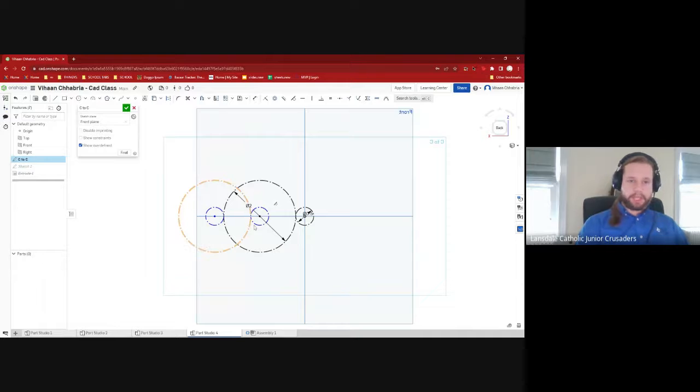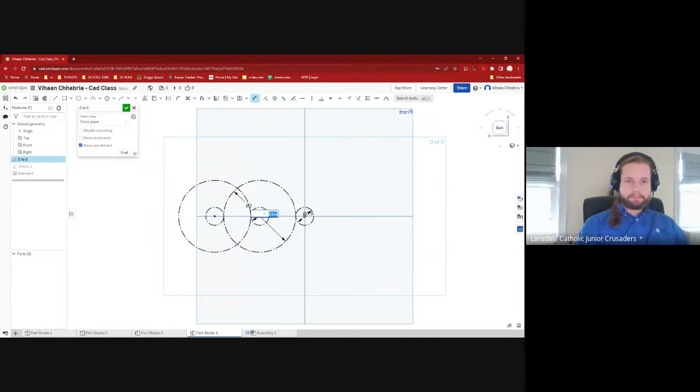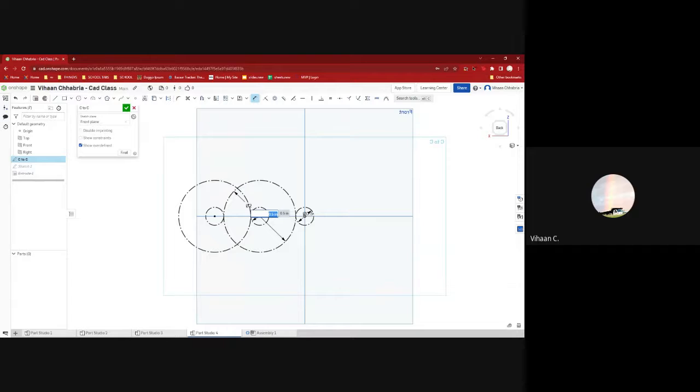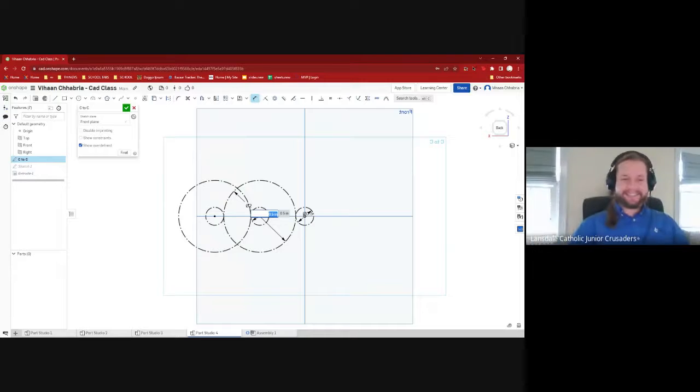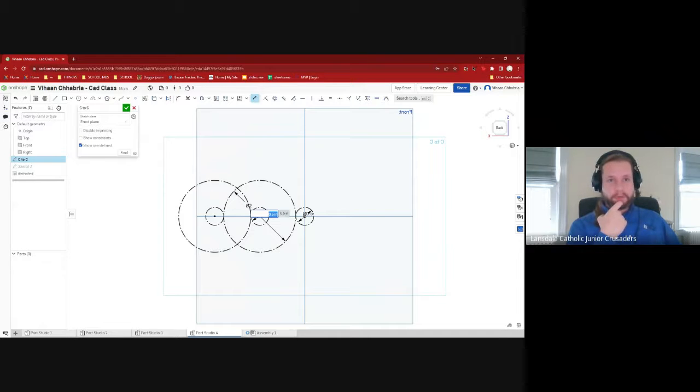And then you're going to change that. So do another dimension, which is the D key for a shortcut. And do you remember the equation? It's the gears on the divided teeth. The teeth divided by the DP. Yes, good. The diametrical pitch is the word. It's kind of a weird word, but try 12 and see what happens. And your model will automatically update once you do this.